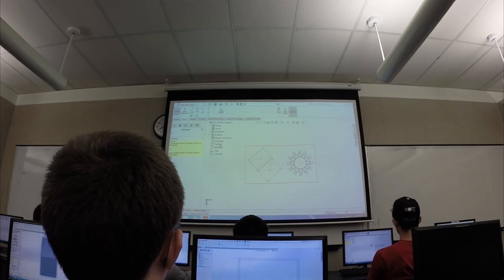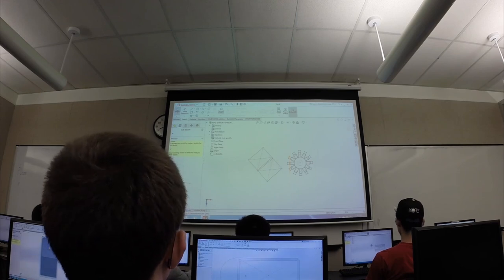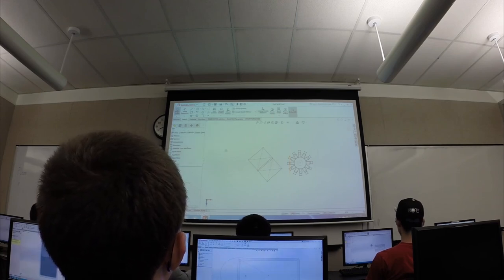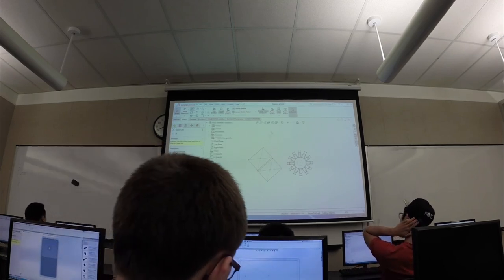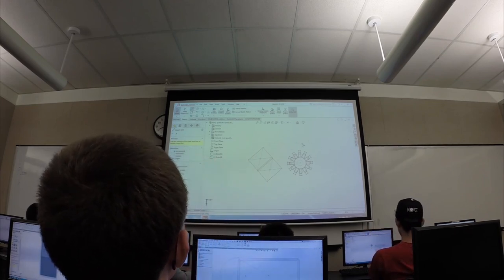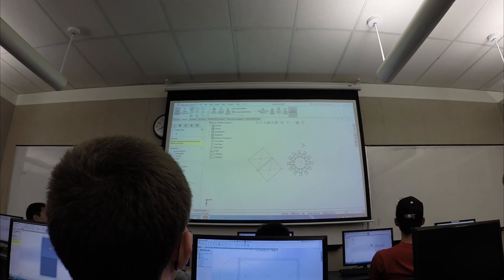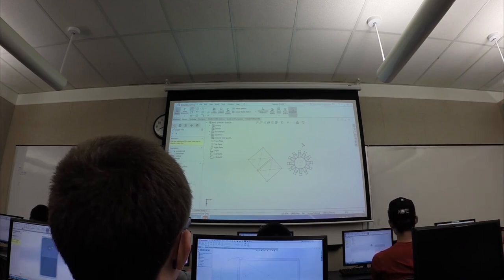We initially made this first sketch on the top plane. So let's say we want to make it on the right plane this time. While sketch is selected, we're gonna click on this right plane. Cool. Now, it might not have changed anything by the looks of it, but try drawing a line. You don't see your line anywhere. The reason is that you're looking at it from this direction right now, so the line is infinitely thin. You can't really see that line, right?